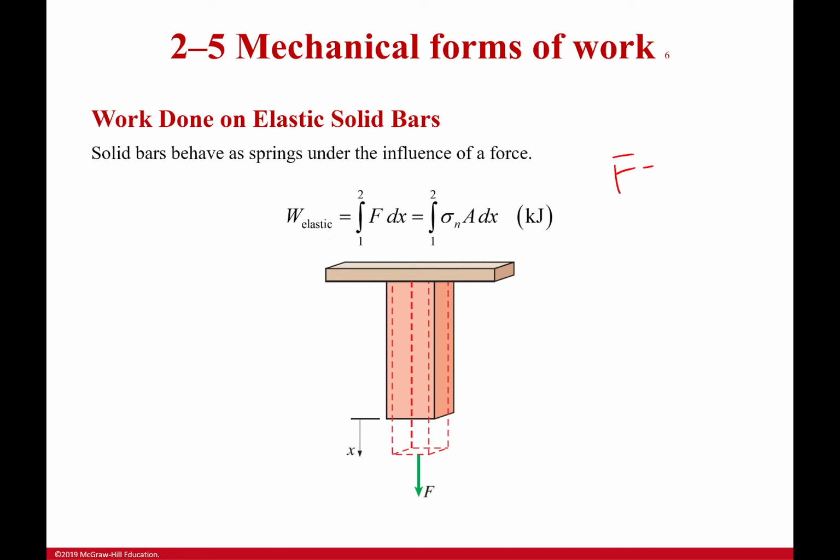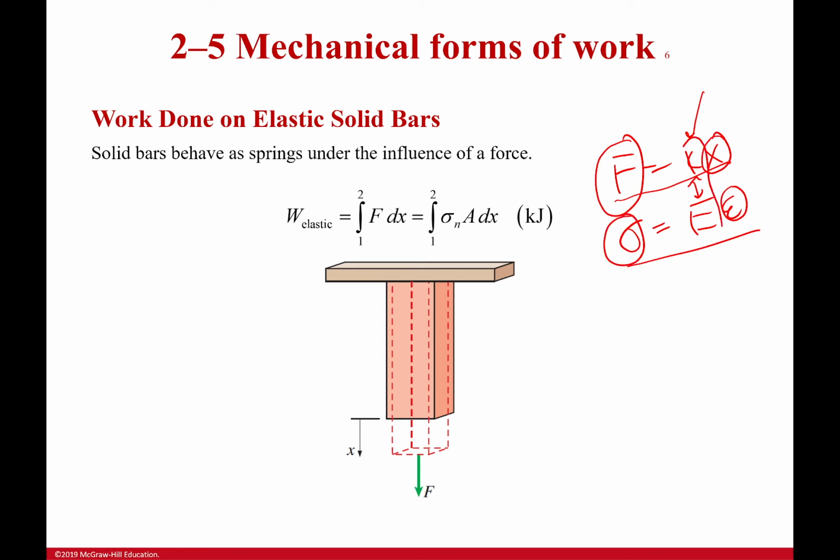The analogy here is that force is equal to kx for a spring, and stress is equal to the modulus of elasticity times the strain for a material. So one's called the spring constant, one's called the stiffness. The stronger your spring is, the more stiff it is, the less likely it wants to stretch. So you can see that these have very similar forms. We have something analogous to how much it's moving, something like a force, and then something that is all about how stiff and hard it is to stretch. How much force do you have to apply to get it going?